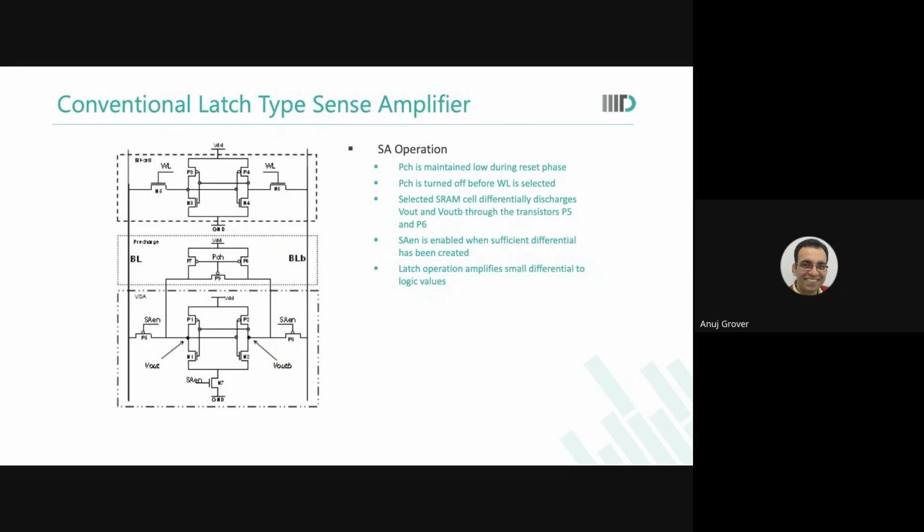Now, if this sense amplifier or if this chip was being manufactured over here, then transistor B will seem to have higher VT than transistor A. If I would manufacture it here, both may have same. So what is happening is that depending on where I am placing my sense amplifier, my offset requirement would change significantly.